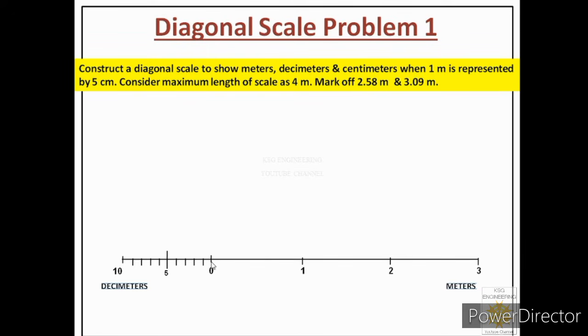Now come back to this smallest part again. This part is representing 1 decimeter, but I have to divide it in such a manner that I get a part of a centimeter, because I have to convert this part into a centimeter scale. For that I have to see the relation between these two units. I know 1 decimeter is equal to 10 centimeters. Now this is a part of 1 decimeter, so to convert it into a centimeter scale, I have to show 10 divisions over here. So I have decided that for this smallest division, the number of parts will be 10.